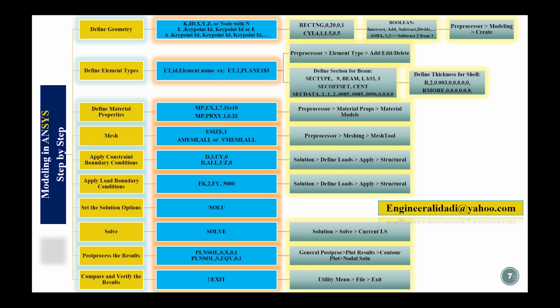The default analysis type in ANSYS APDL is static. Thus, in this step for performing linear static analysis, it is enough to just run the analysis. After the analysis is done, review the results such as deformation shape and reaction force. We have a separate comprehensive tutorial video about results in ANSYS. I recommend you watch it.